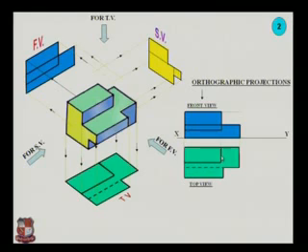Draw the horizontal projection up to the 45 degree line. Extend this projection from the 45 degree line in the upward direction. Same, draw the horizontal projection from the front view in the horizontal direction. So we will get the side view of this object. It is a simple method to draw the orthographic projection for the first angle projection method. It is a left hand side view.